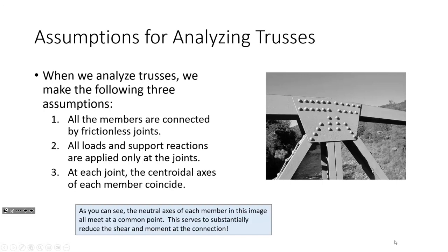That is intended to ensure that when you are analyzing the structure, the loads are going directly to the joints, so they are only experiencing axial forces. Again, no shears, no moments. And the third assumption goes to that effect as well.